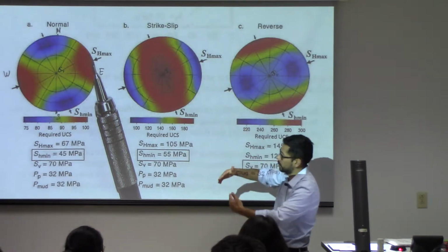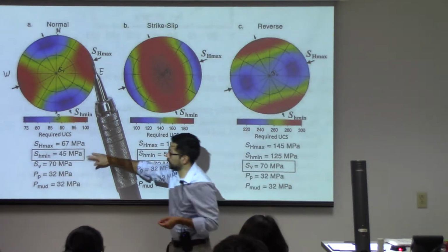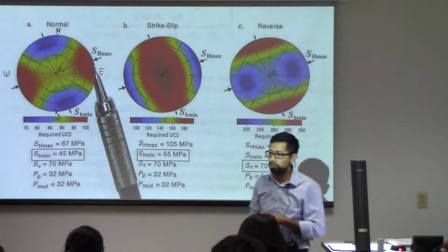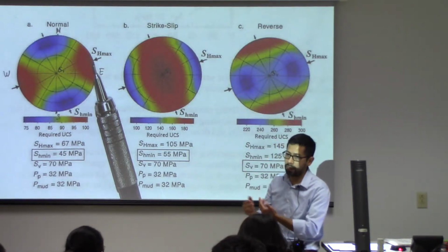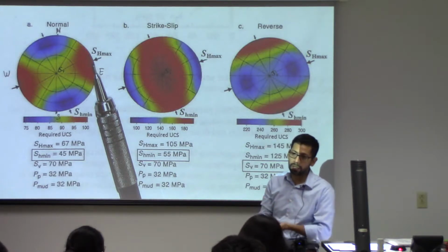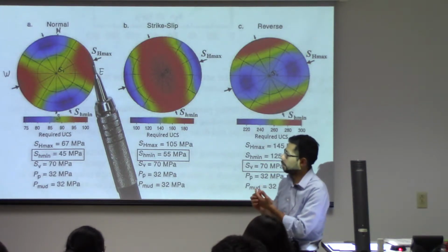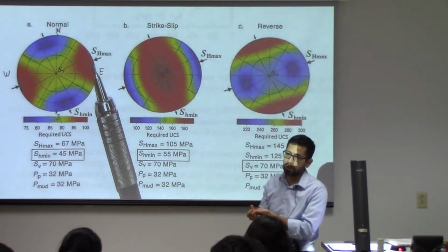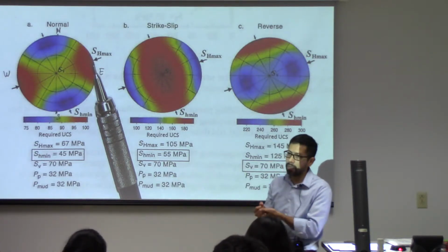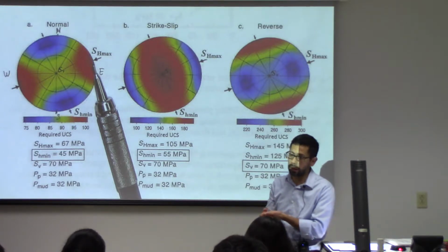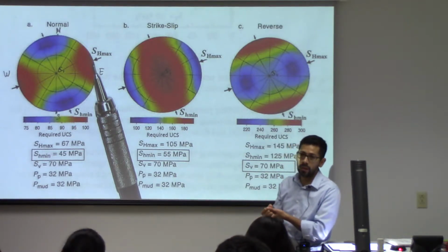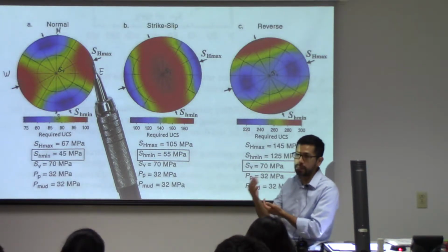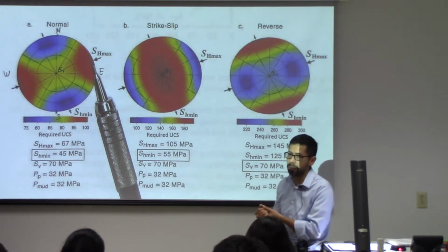The direction of the stresses and the relative difference between the stresses is important because that's going to tell you lots of things, like, for example, orientation of hydraulic fractures, orientation of faults, the most likely orientation of faults to be reactivated in shear, and also what is the best and the worst condition for drilling a deviated wellbore in a given location.